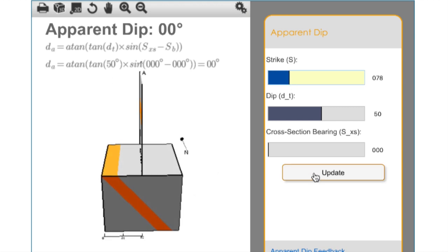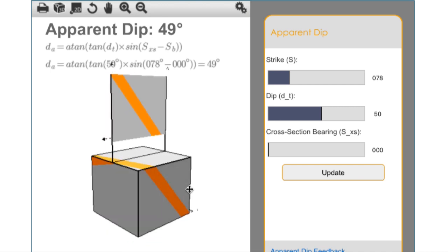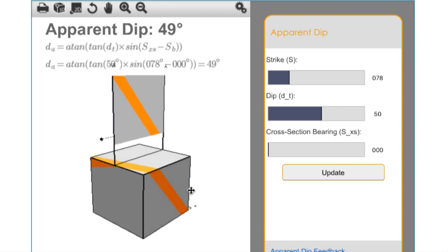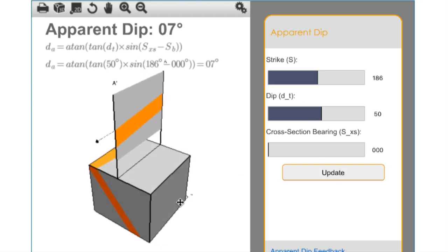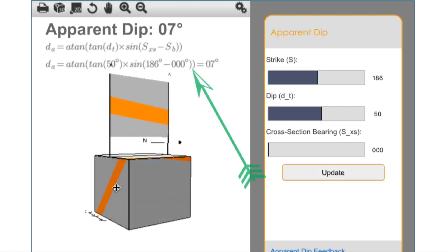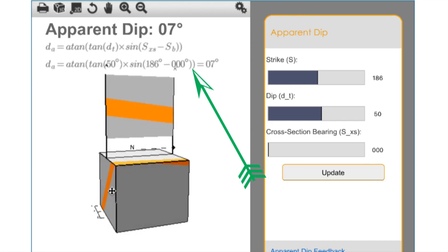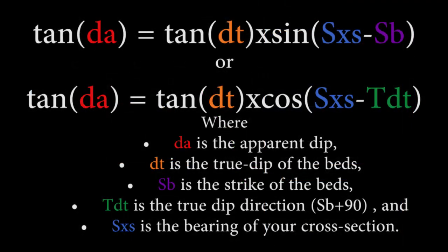But if the plane intersects the surface at anything other than 90 degrees, it will show an apparent dip, less than true dip. If you think about it, a plane hitting a surface head-on will look like a horizontal line, even though the planar feature making it is dipping. But not all hope is lost, as we can use a little trigonometry to calculate the true dip as the plane of observation cuts the plane of interest from its apparent dip.